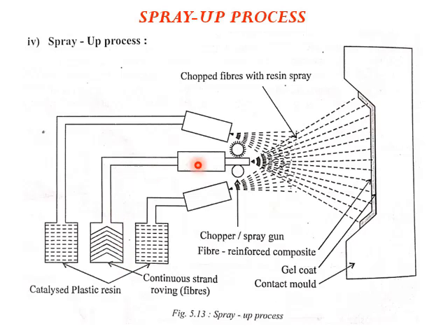And at the end of this, a fiber rolling component, so we are going to have choppers. Choppers are mounted in order to cut the fibers to a required length. You can see the action at this end of the nozzles. From the top and the bottom, there is a spray which is continuously spread over these discontinuous fibers.